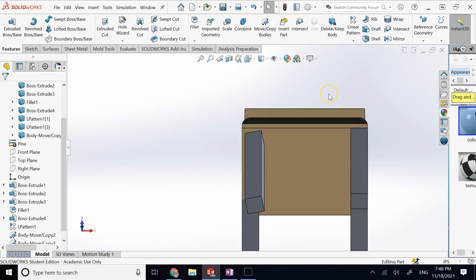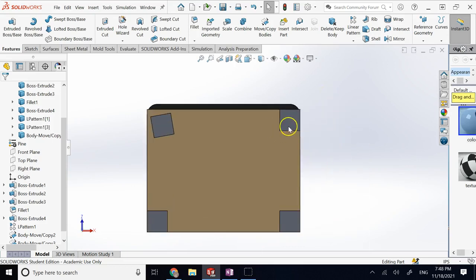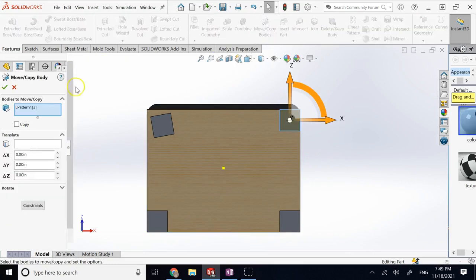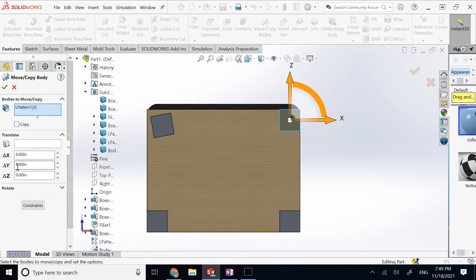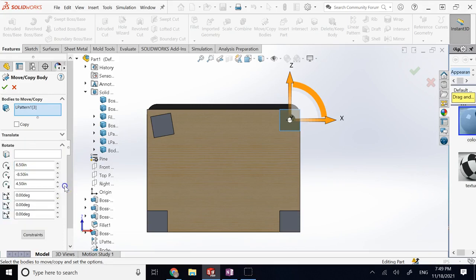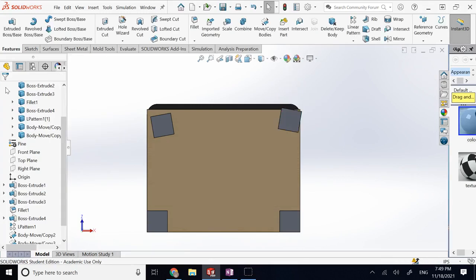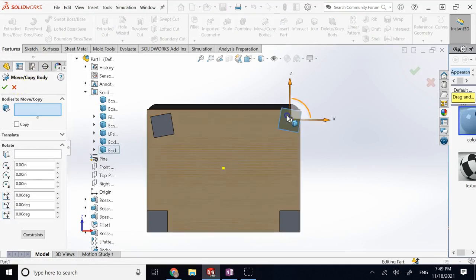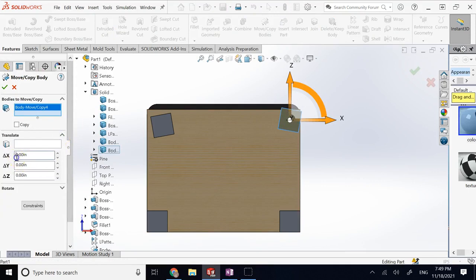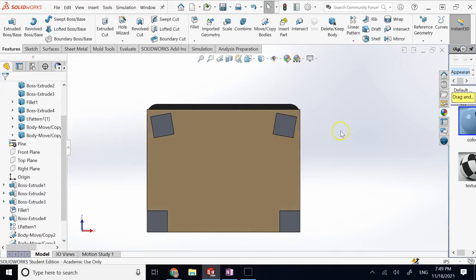So these are similar to the constraints that you had in assembly. And then let's say I can do a similar thing on this one too, right? So for this one, let's say I want +10 degree rotation, and I get something like that. And again, all I need to do is to apply some motion to this one, and this time I need to move negative 0.5 for X and negative 0.5 for Z to bring it inside like this, right?